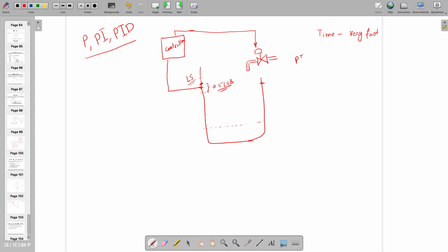As it would reach the minimum of that level, and the level keeps on increasing, the controller will integrate how much. Any instrumentation? Do we have any? Sandeep was instrumentation, but today he is not here. Right? Okay. So the controller will control by how much amount the level is increasing, and it will integrate that. Okay, but we need to understand integrate is going to make the response sluggish.